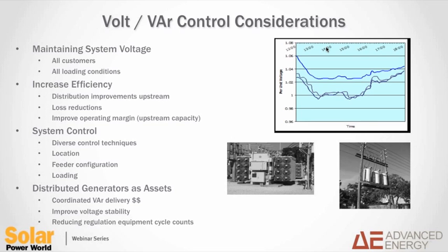You also have to take things into consideration such as feeder configuration. So if there's a fault or some other reason that the utility is motivated to reconfigure an area of the network, then that PV plant may be connected to a feeder with an entirely different load characteristic. So the inverter has to be somewhat reactive to being able to receive a different profile, different curve, different setting, set point, et cetera, to evolve with constant changes in the distribution network due to outages, et cetera.